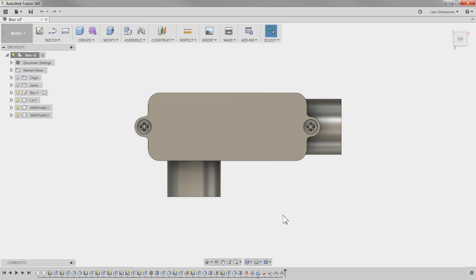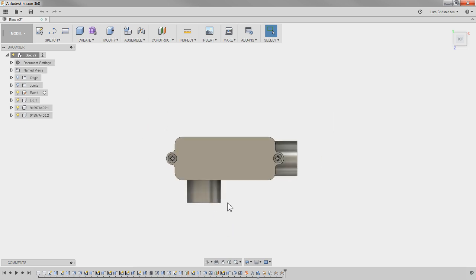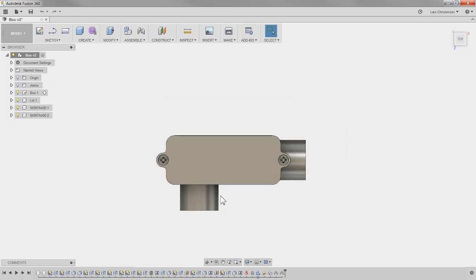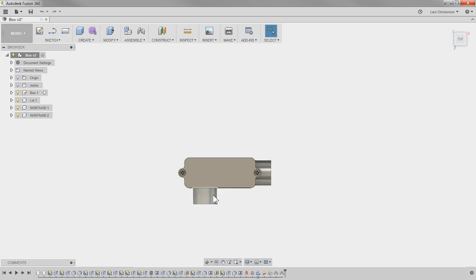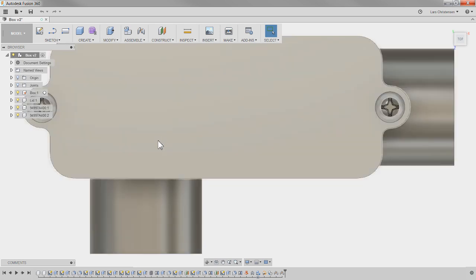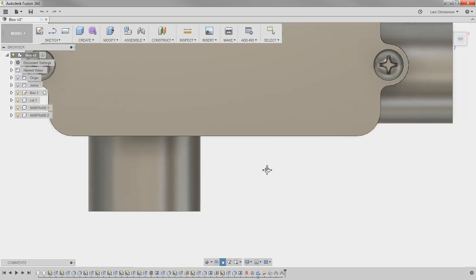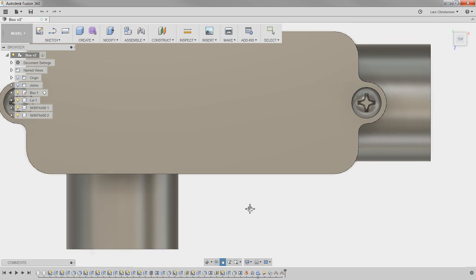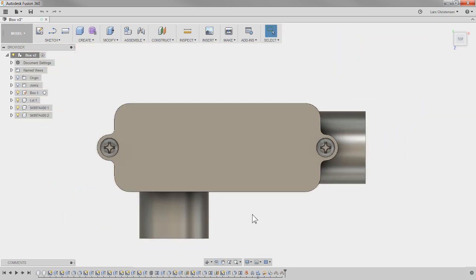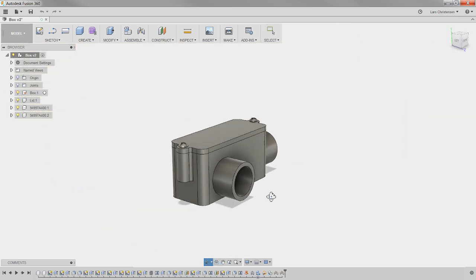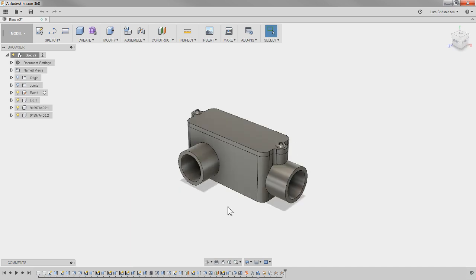Okay. So just to recap here, and again, I apologize for all the confusion. To scroll in and out, middle mouse button. To be able to fit to zoom, just double click on the middle mouse button and it gets right back into zoom. To pan, hold down that middle mouse button and you're panning. And to spin it around, you just hold down the Shift, hold down the middle mouse button, and you are now spinning around.